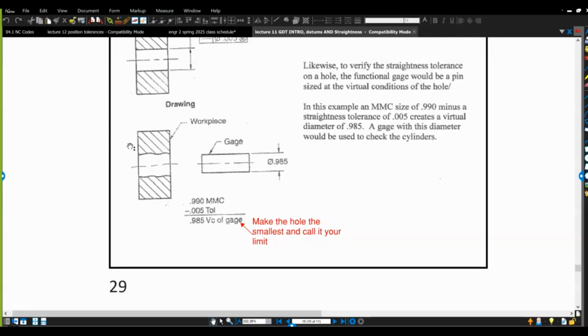Usually when you're putting things together through a bolted condition or through interference pins, you are joining things together, and you have two types of situations. We call it the fixed fastener situation or the floating fastener situation. Fixed fastener is when you're screwing things, because once you screw, that thing will not move. The floating fastener is when you have a plate on the top, a plate on the bottom, you grab a bolt and go all the way through, and then you put a nut at the end. You're going to watch the lectures for this week and learn about it, and also the formula. Does that make sense?